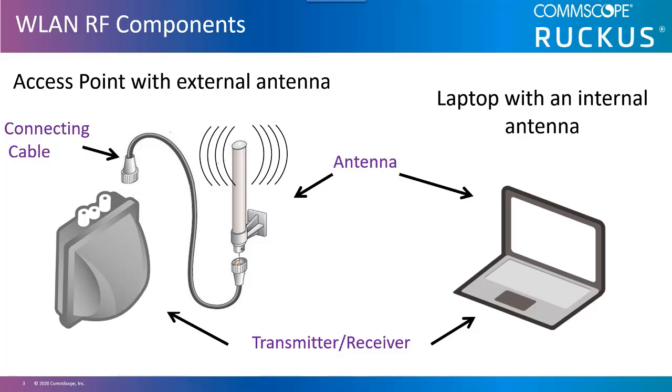The transmitter receives data for transmission and converts it to an oscillating signal, which is then modulated with the data to be sent wirelessly. When the wireless signal includes the data for transmission, it is referred to as the carrier signal. The power level of the transmitter's amplifier determines the amplitude of the wave, and once placed into the air via the antenna, it becomes an RF signal.